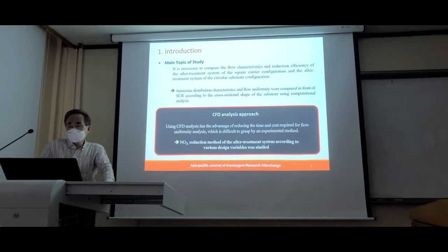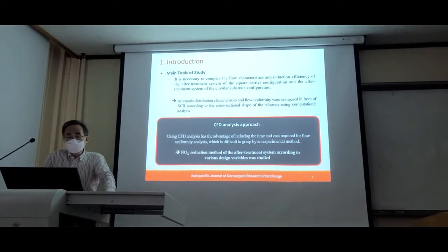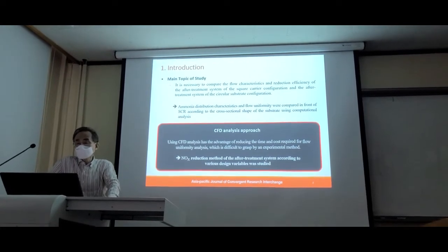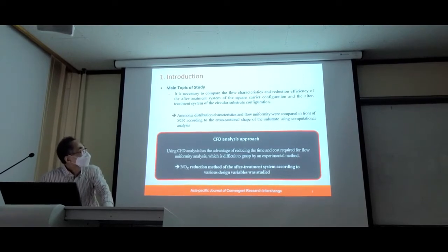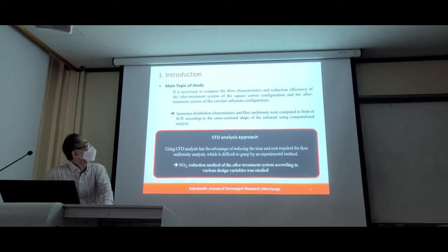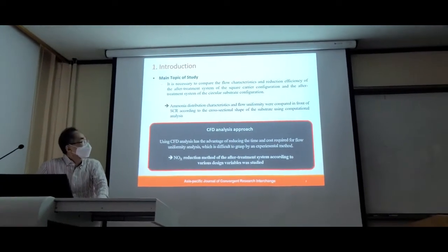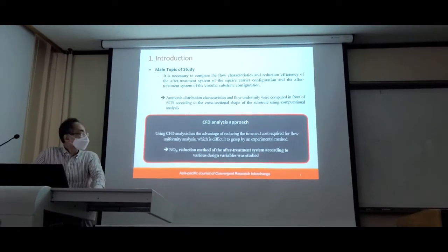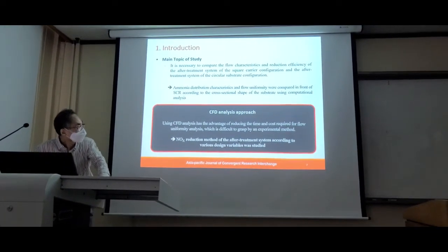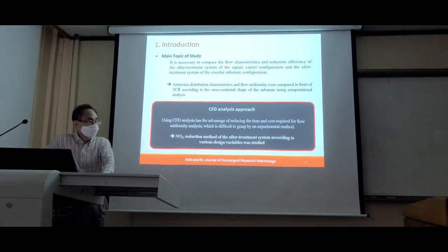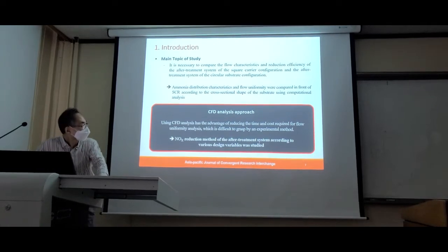It is necessary to compare the flow characteristics and reduction efficiency of the after treatment system of a scale carrier substrate configuration, and the after treatment system of circular substrate configuration. Basically, we apply this CFD technology to understand the inside flow in the substrate.